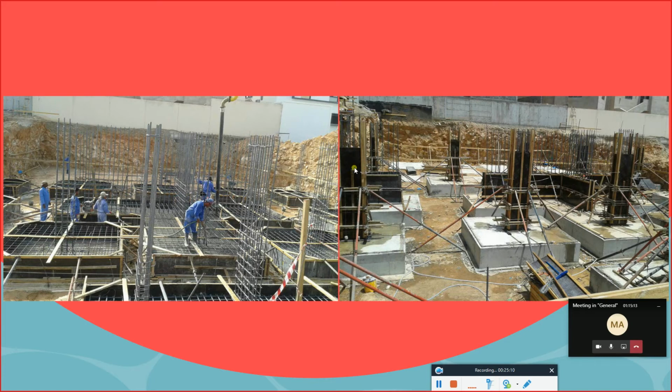And then you can see here they have started the starter column. Call it a foundation column or a starter column. Starter column is a column between the foundation and the other upper columns. And this is normally going to go for around 1 to 1.5 meter.